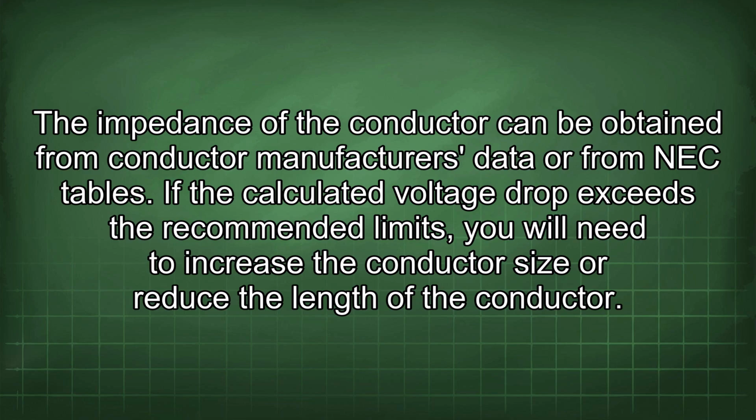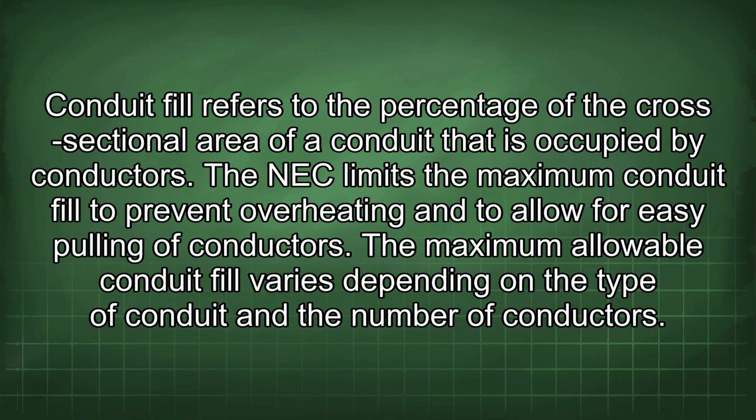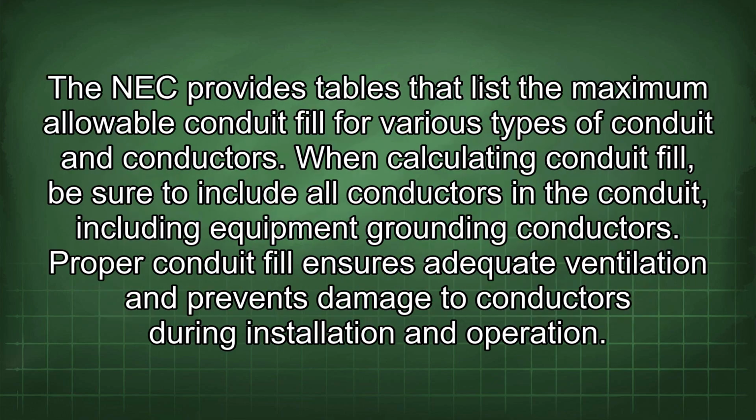Conduit fill refers to the percentage of the cross-sectional area of a conduit that is occupied by conductors. The NEC limits the maximum conduit fill to prevent overheating and to allow for easy pulling of conductors. The maximum allowable conduit fill varies depending on the type of conduit and the number of conductors. The NEC provides tables that list the maximum allowable conduit fill for various types of conduit and conductors.